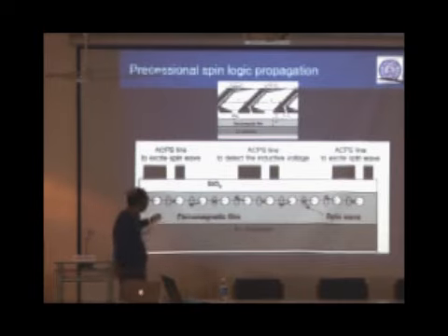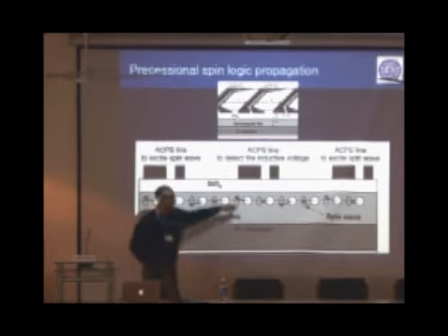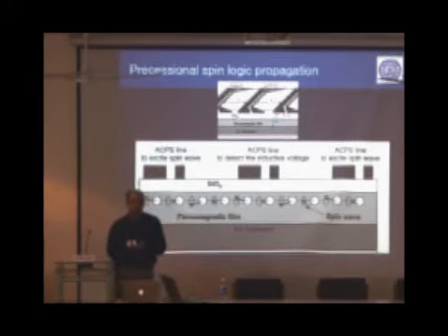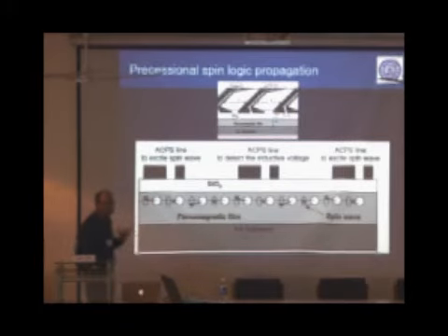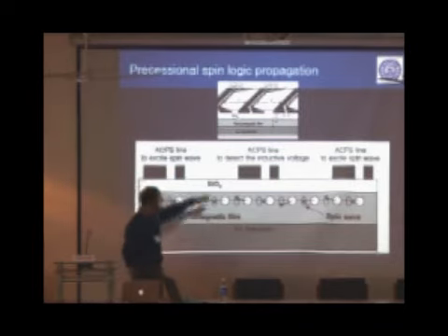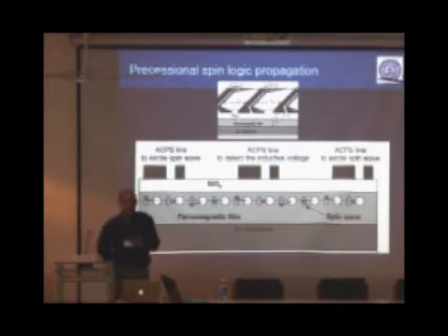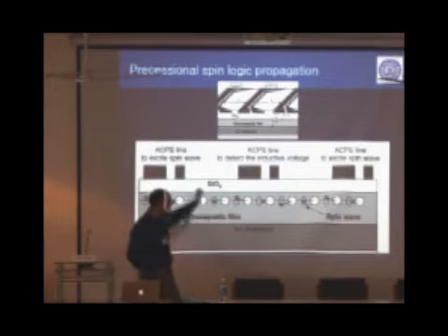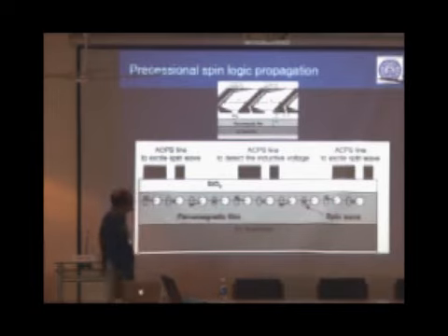So at any time, the logic signal here versus this logic signal here would have a phase lag. So you have to always remember the phase lag, but that is directly related to the distance, the way you make the transmission lines. So if you apply the correct phase signal, if you launch a wave here, you can reach the other side and receive it with the right phase. You just have to apply a small delta phi depending on the distance traveled.